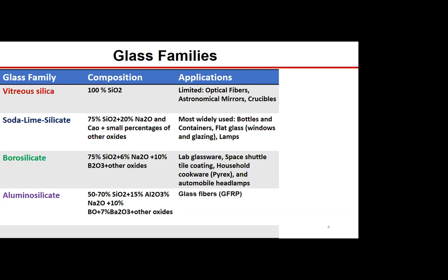Yeah. And I was also interested in when you sandwich them, that is, you take different glass layers and sandwich them without chemically melting them and fusing them. So in this case, let's say we take a sample of flat glass made from soda lime silicate, with the same sample made from borosilicate, and we sandwich them together, and we look at the strength. Again, what will determine the strength is the weakest link in this case. The one that has the lowest value of fracture toughness will fail, and therefore the structure will fail.